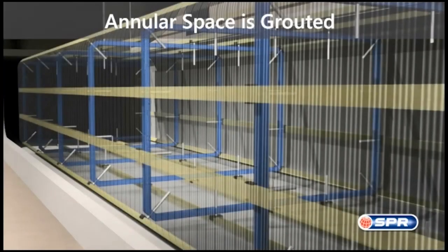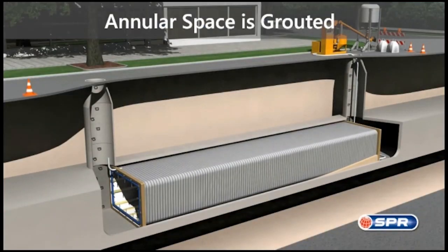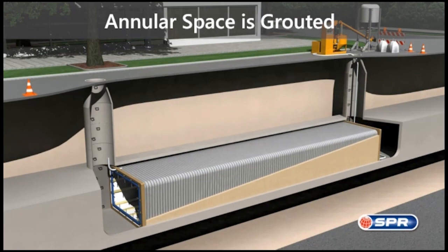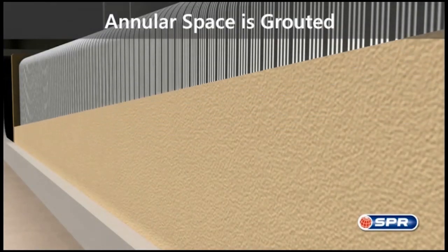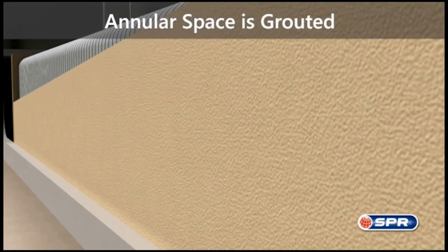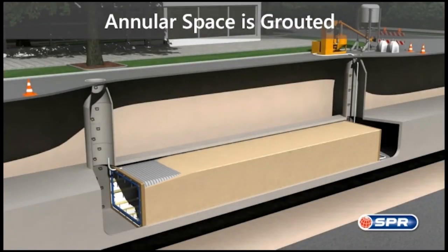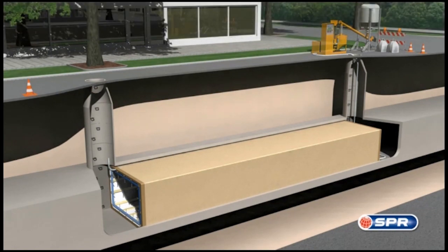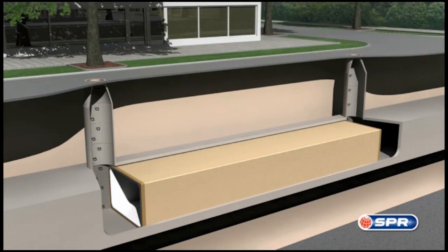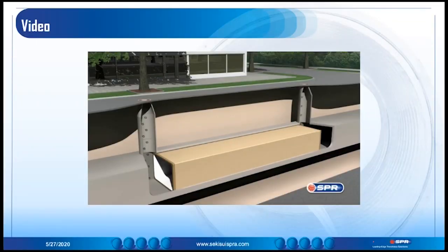Typically, simple bracing is used. As demonstrated here, just conceptually, we will reinforce the liner to prevent liner flotation during the installation process. And then the operator will come back in and perform annular space grouting. This can be done in a variety of different ways using structural or non-structural grouts and single to multi-lifts, depending on the compressive strength of the grout, the project, the run length, etc. And that would be part of our submittals to our contractor.